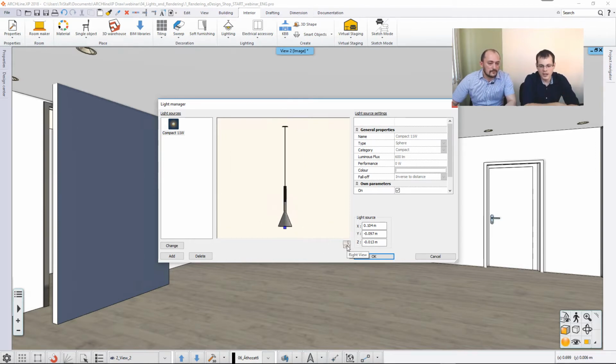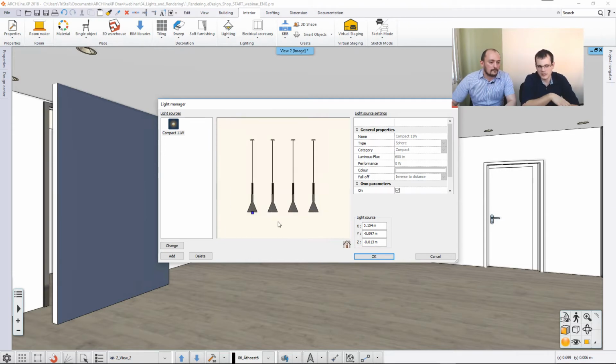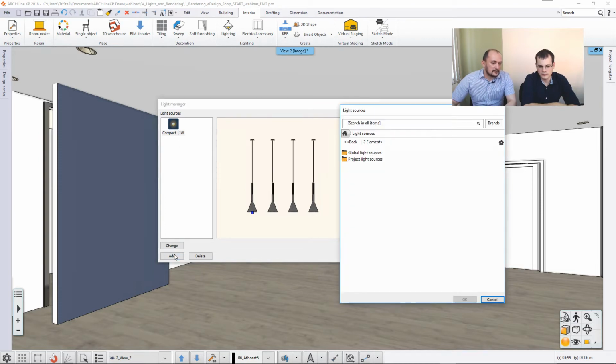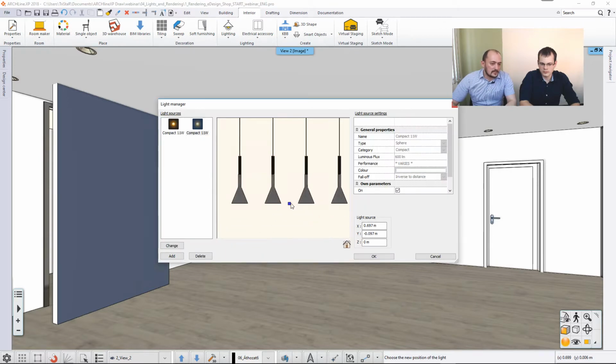Now you are lucky. So how do you add another copy of this light source 3 additional times? Well, if I would like to add another one, then I can just click on add, and I can select a light source. I can even go with my project light sources if I already use one. So I just select this one, okay, and then it's added again to the center. I can move it, and I can repeat this 4 times. And so I will have 4 separate light sources. And then when I hit OK...